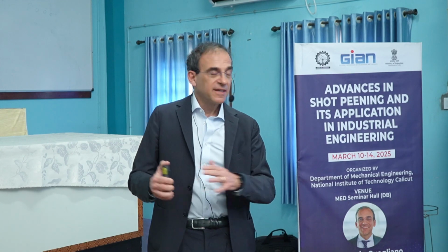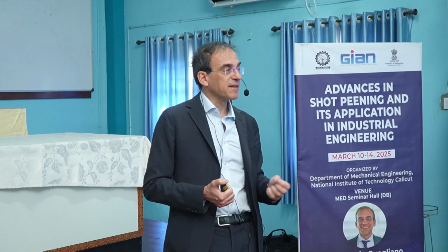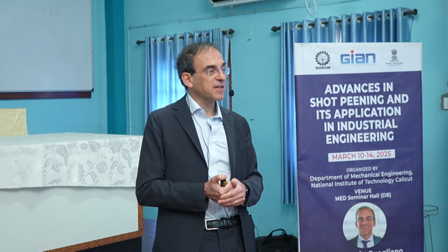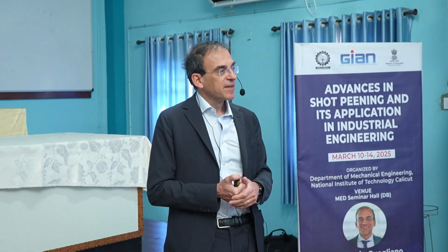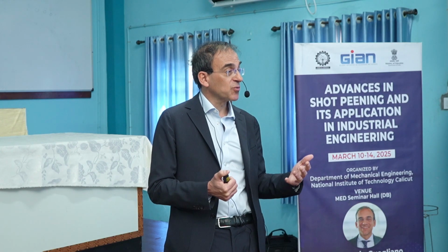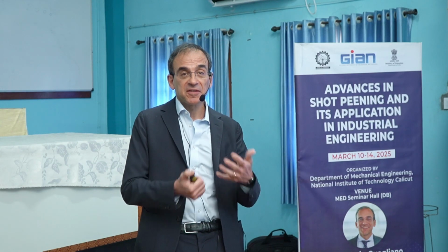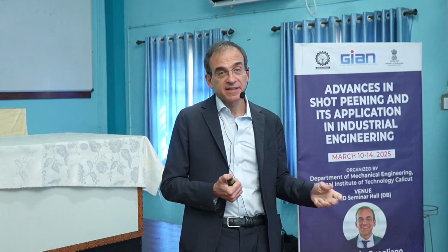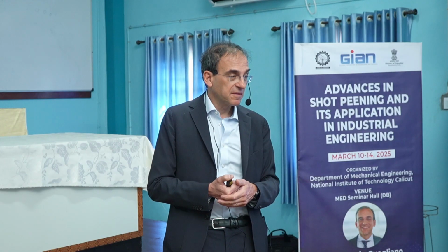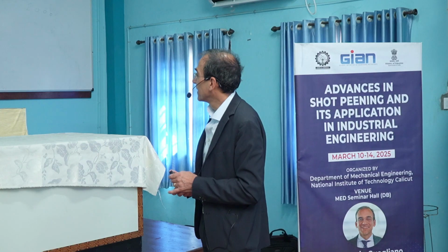And then, if you look at the titles, I also use shot peening not only for fatigue, but I explore the possible application of shot peening in other fields. One of these is the application in biomedical devices, that is to say, to improve the cell adhesion, the osseointegration for prosthesis, or to reduce the bacteria adhesion and so avoid infection. With interesting results.